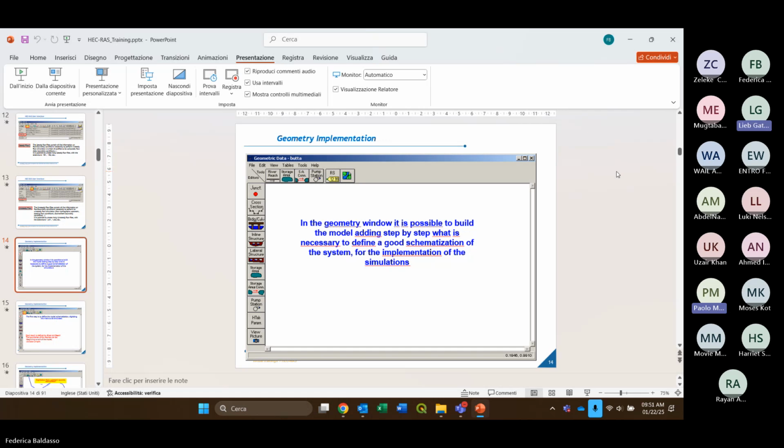A topographic survey can be in the form of cross sections, which means you survey the out-of-water part with traditional ground topography, and then you use an ADCP, for example, to merge it with the part of the cross section that is underwater. This is the most usual option.